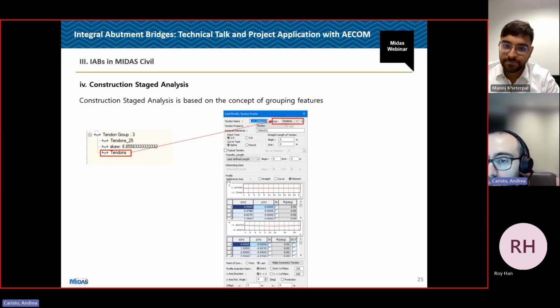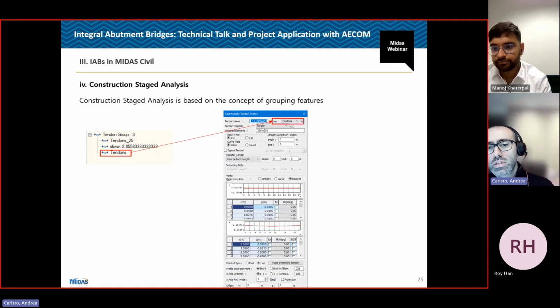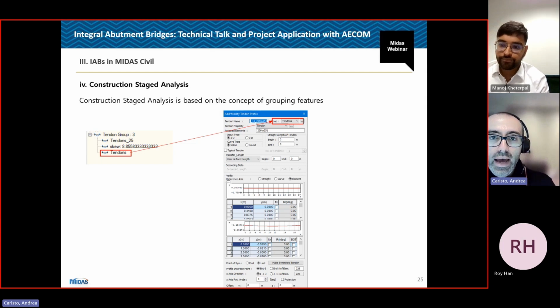But the idea behind pre-stressed concrete is really to enhance the bearing capabilities of our elements by assigning, let's call it, artificial pre-stress, an external force through a specific element that's our tendon. It's a high grade steel tendon, which is stressed, tensioned, and then locked in place and released, and it basically introduces a compression into our beam.